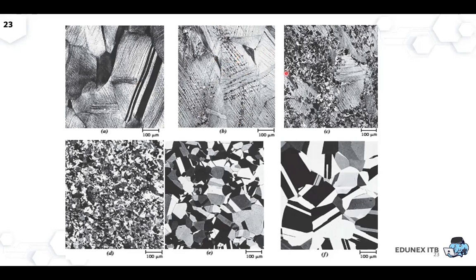After that, the grains continue to recrystallize and become bigger than the previous ones. When we have recrystallization with small grains and we hold it at temperature, the small grains increase in size and become this one, so they grow.